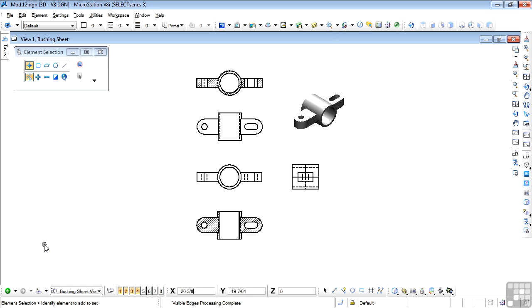If the objects are moved in the source design, the saved views will need to be resaved and the views repositioned in the sheet design. On the other hand, you can pan the views in the source design without affecting the saved views. If you need to regain the original source views after panning, simply apply the saved view to that view window.